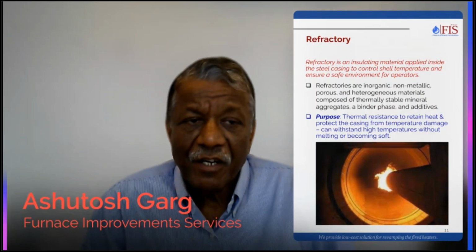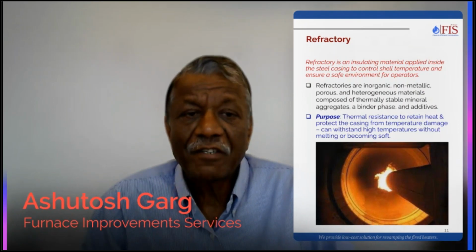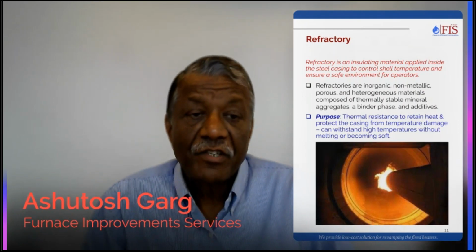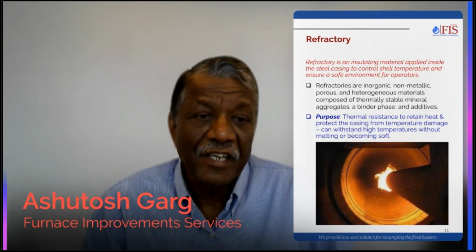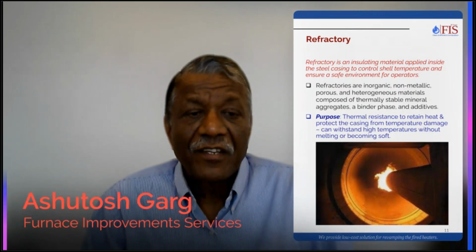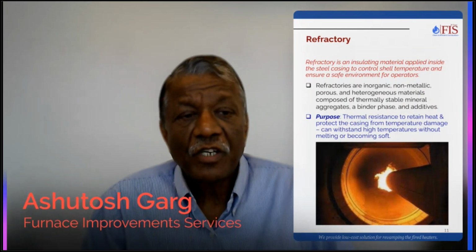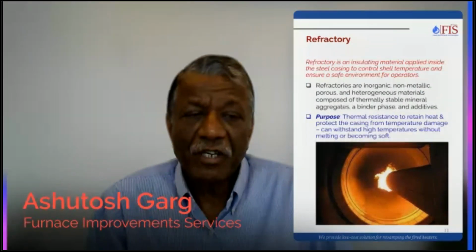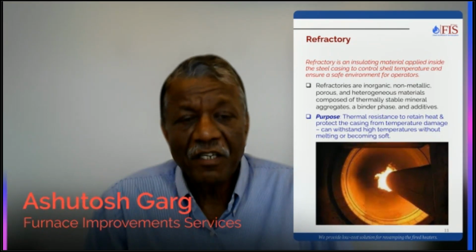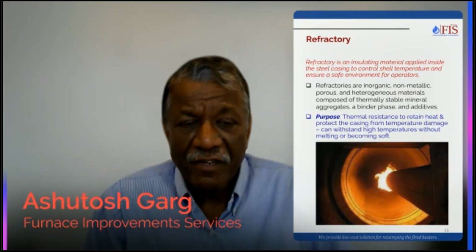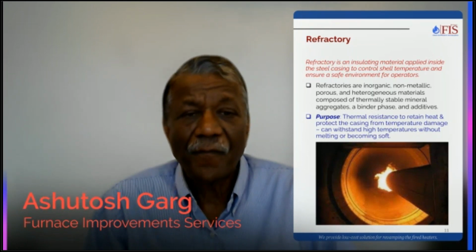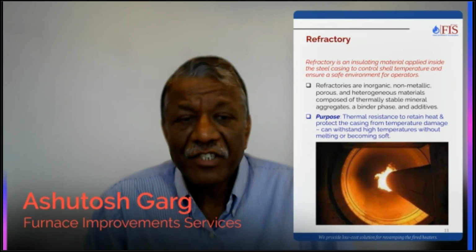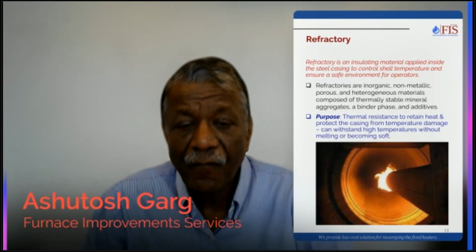Refractories are non-metallic, porous, and heterogeneous materials, which are thermally stable in the sense they can go up to 3000 degrees F. The purpose is to create a thermal resistance so that you can contain the high temperature in the radiant section, convection section, and burners. So that's basically the definition of refractory.